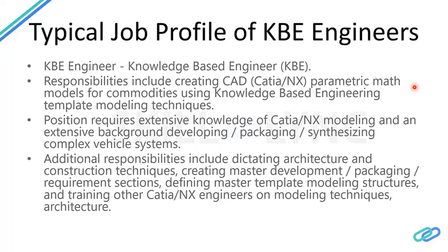And functional setup and sizing. During our KB detailed training, I'll be teaching you how the inputs are derived, CDD, the studio release surfaces, for creating each part, how the first flanges are created, how the parting line is created considering the tooling aspect, and how the parting line is considered to derive the gap between the two parts. All these things will come into the picture in functional setup and sizing, geometry and interface definition.